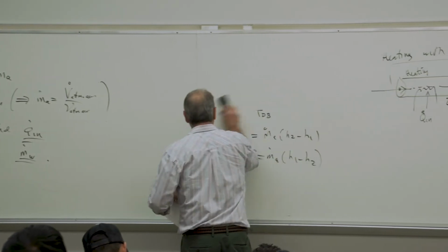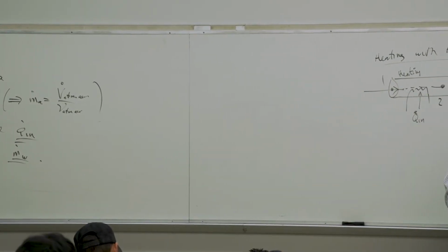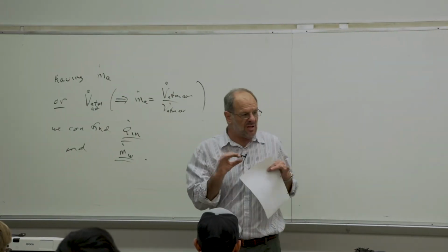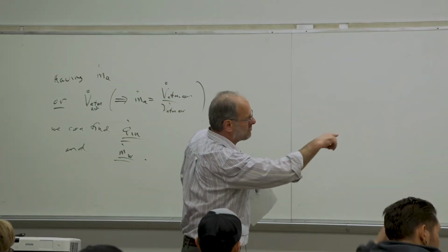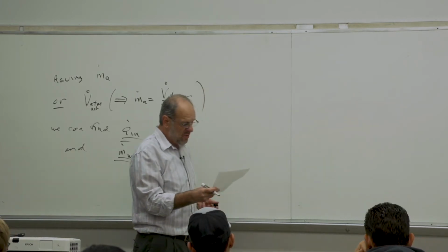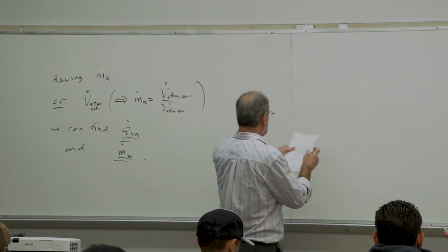Another thing I want to note, and this is not actually presented in the textbook, I'm not sure why, is that typically the unknown for this problem is going to be HW. We want to know what temperature of water we need for this particular air conditioning process.